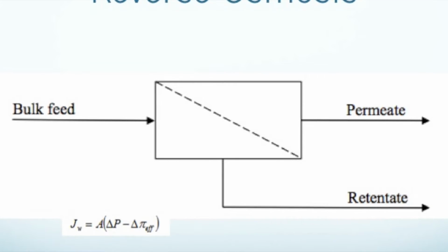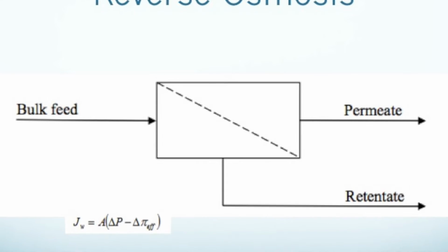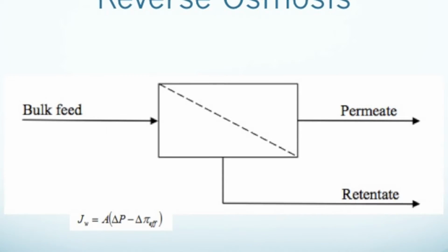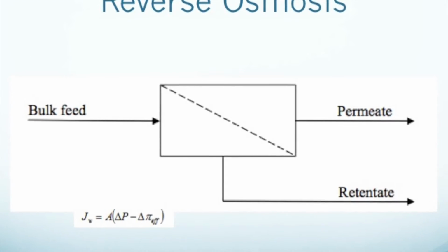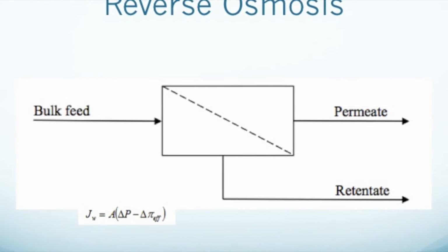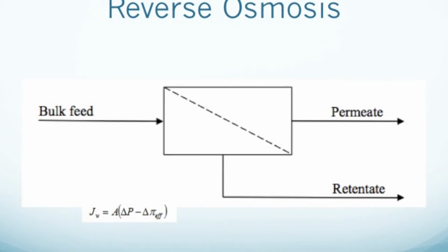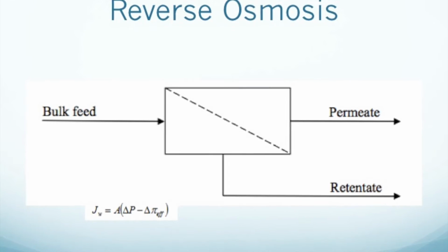Reverse osmosis is a pressure-driven process and requires a high energy usage compared to forward osmosis. A saltwater solution is purified as hydraulic pressure forces water through a membrane. The selective membrane rejects the permeation of salt, leaving a freshwater product stream.